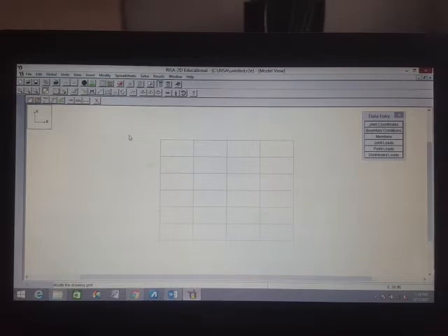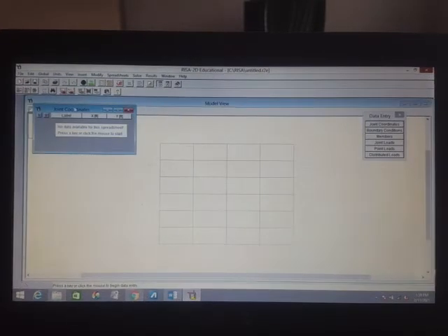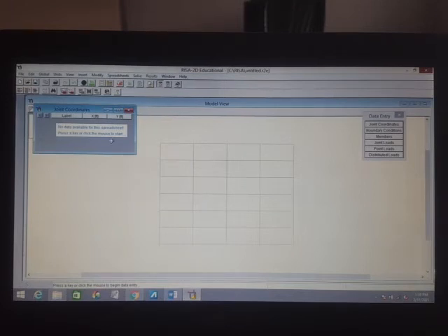So step number 6 is we'll have to input the data. So data entry is, if it's not open, you can just click this D. That's data entry, and the other one, I think, is the results entry. For the data entry, we'll first define our joint coordinates. For the joints, it says here no data available for this spreadsheet. So we'll click this, and then we will label the joints.